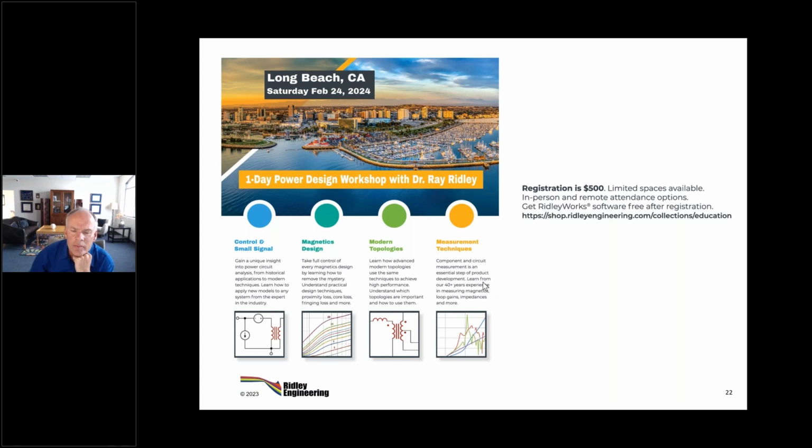Does Dowell's equation assume a cylinder? Yes, it does. Just a note on calculating the gap loss. You can put that gap and the turns into a piece of finite element software, but you're going to have a devil of a time describing it because the turns spiral up around a single turn. By the time it's gone around a turn, it's gone more than one gap away. So at every little point around that circumference, it's a different distance from the gap. So you've got to do a really good three-dimensional model to get that.